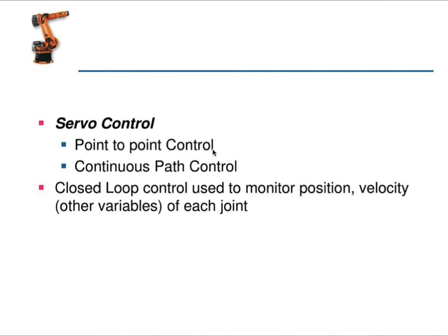In PTP control, individual positions of the robot arm are recorded into memory, and these positions are not limited to the mechanical stops set for each joint as in the case of limited sequence robots. Feedback control is used during the motion cycles to ascertain that the individual joints have achieved the desired location defined in the program.